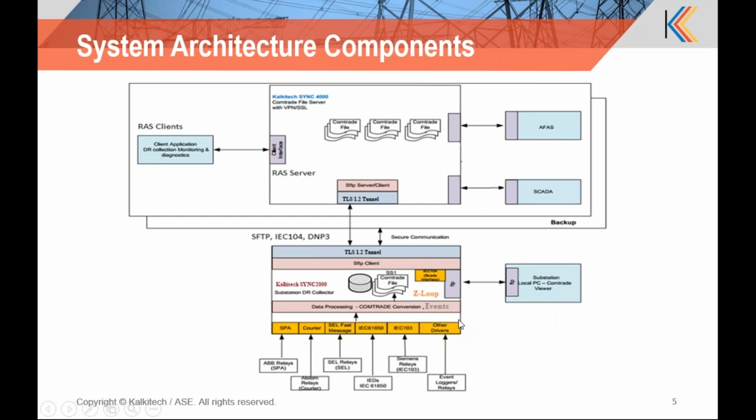As I have mentioned, this is SYNC2000. There can be multiple protocol drivers collecting data from multiple relays, and we have all these drivers available, whether it is PA, Courier, Schneider relay, SEL Fast Message protocol, 61850 protocol, 103 protocol, and other drivers like GE and custom Modbus.